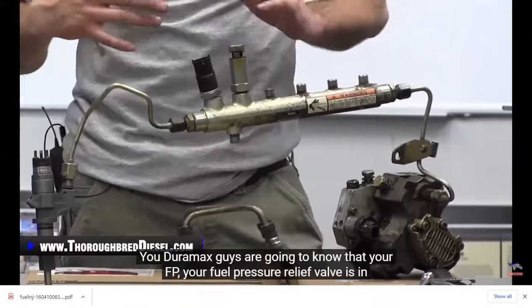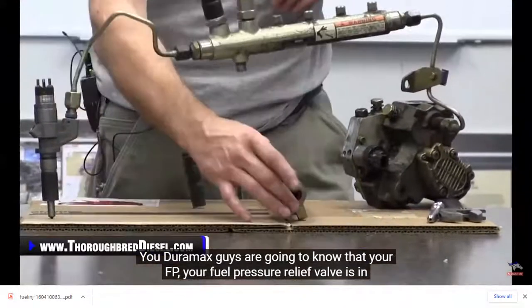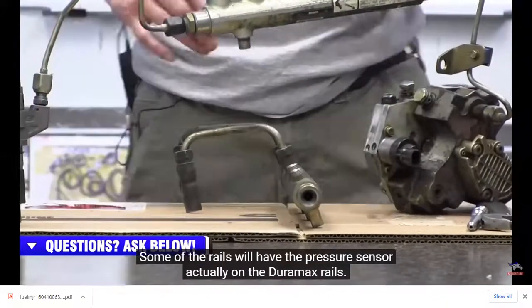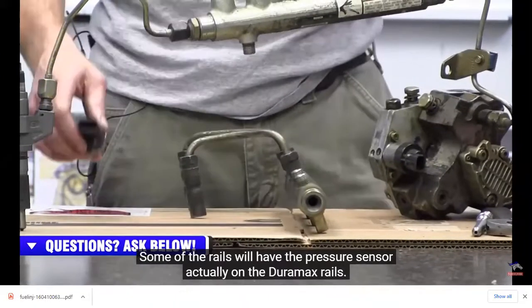You Duramax guys are going to know that your FP, your fuel pressure relief valve, is in the back of the rail. Some of the rails will have the pressure sensor actually on the Duramax rails.